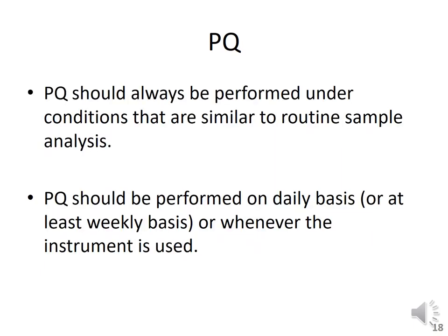Now, the performance qualification, PQ, should always be performed under conditions that are similar to the routine sample analysis. That means it is important that you do your performance qualification under all those conditions which are similar to the routine sample analysis. If you are doing the performance qualification under somewhat different conditions, that will not be worth working on, right? Performance qualification should be performed on a daily basis or at least weekly, or whenever the instrument is used.